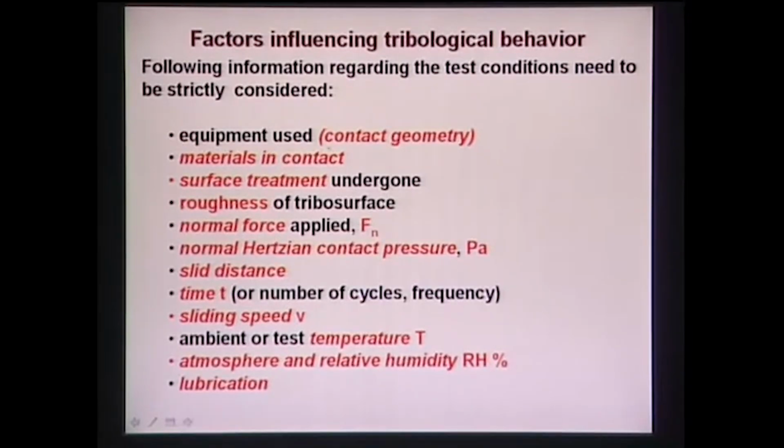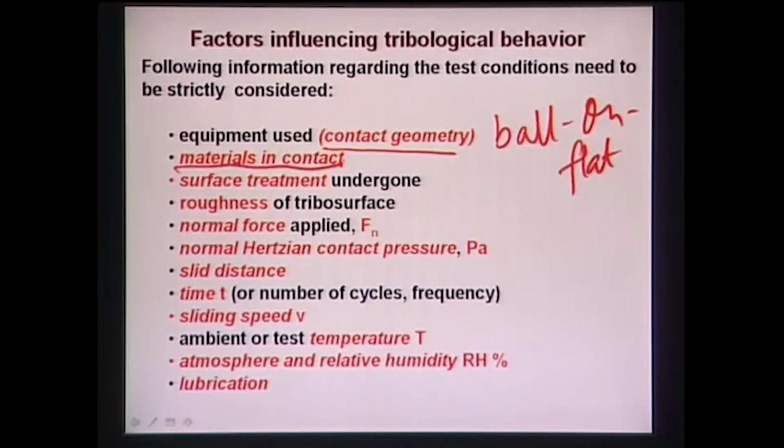Now let us look at the different factors which will influence the tribological behavior. First one is contact geometry, whether it's a ball on flat or a pin on dish type of geometry, that is important. Then materials in contact. As I said, tribology depends on the material parameters as well as operating parameters. So the moment you change the mating solid, that is the other material in contact with the nominal material, the tribological properties will also change.